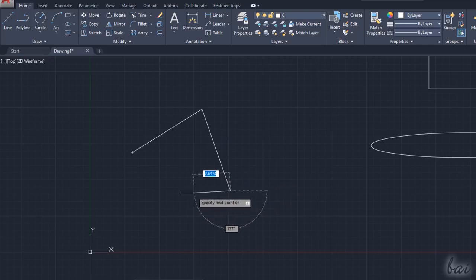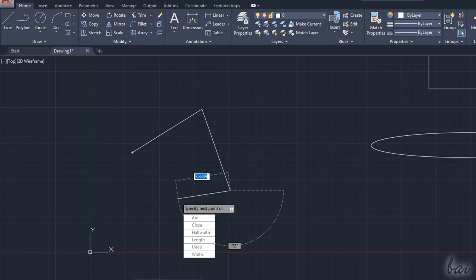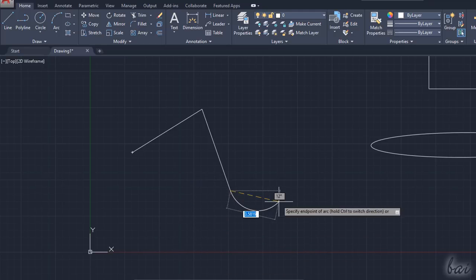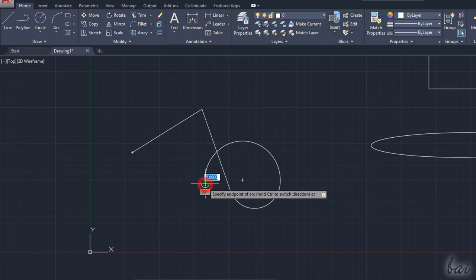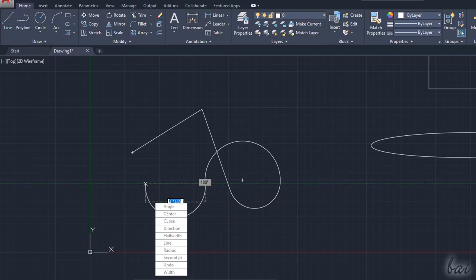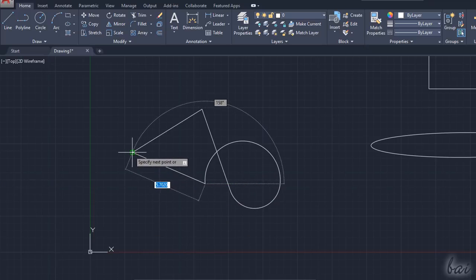In addition, you can use your up and down arrow keys to browse inside the list of options within the gray dialog box, in order to change the way to draw the object or specify its properties depending on the current drawing step. For example, you can choose Arc to start drawing curved sides and Line to return to straight sides. Remember to use the Enter key to apply.